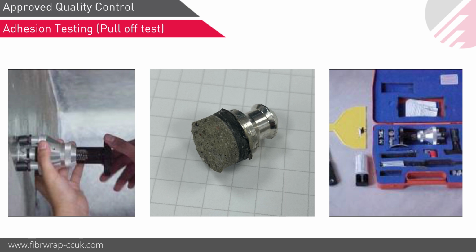But they should always ask the contractor to do a pull-off test on any bond critical application like beam strengthening, slab strengthening. This bond test is slightly different than your standard concrete pull-off test, because in that we look out for a number in terms of pull-out strength. But here we are more interested in mode of failure. So after 100% curing of FRP, we perform this pull-off test from a sacrificial patch on the same area.